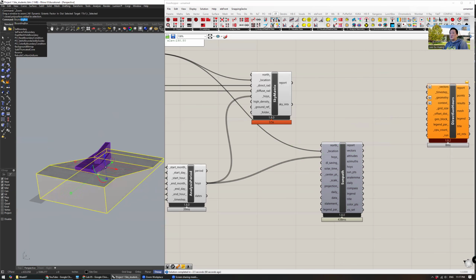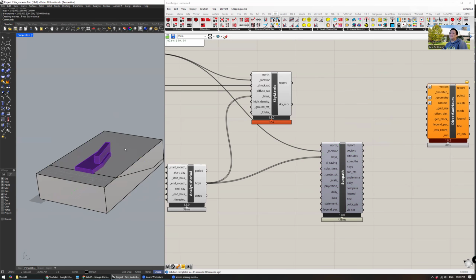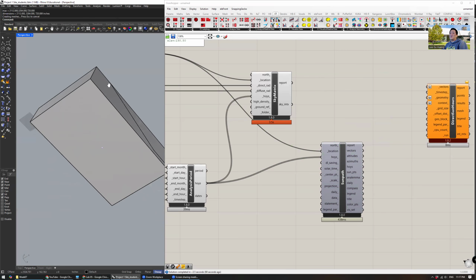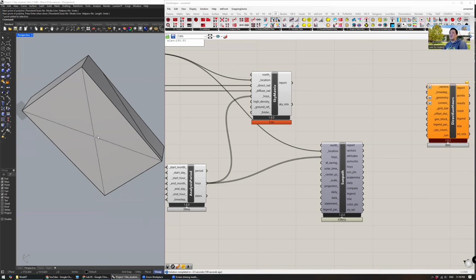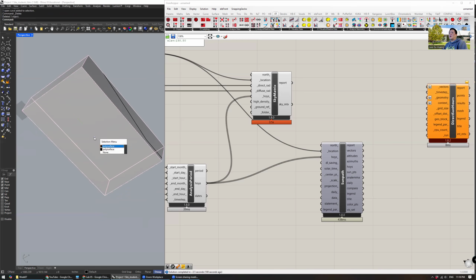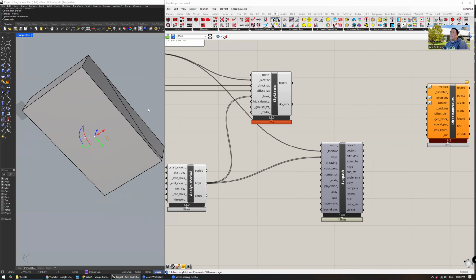If you run a bounding box on it, and then you can see in the bottom, if you drew a cross or drew a polyline, crossing it like that, its intersection is the midpoint, right? I already have a point there because I did it earlier. Or midpoint of that line essentially is the center, right? So this is where I would put the point for the center point.